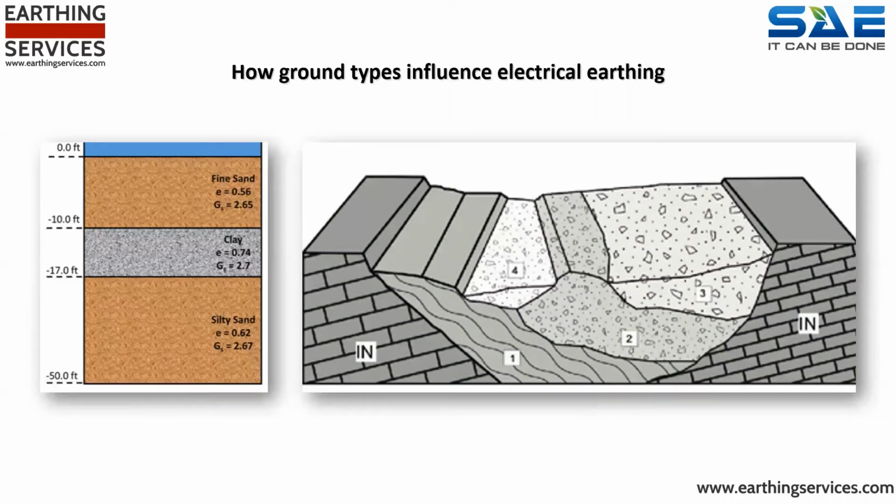To provide a shorter time-framed example, a common construction process that is frequently used when establishing a site is remediation, whereby a ground mass is excavated and essentially replaced with ballast-type material, which may provide greater stability for the construction activities to follow. That being stated, the ground mass that was previously present will discharge electrical current in a significantly different manner to the crushed rock, which is often used during remediation. As such, remediation activities should always be considered as part of the electrical earthing system design.